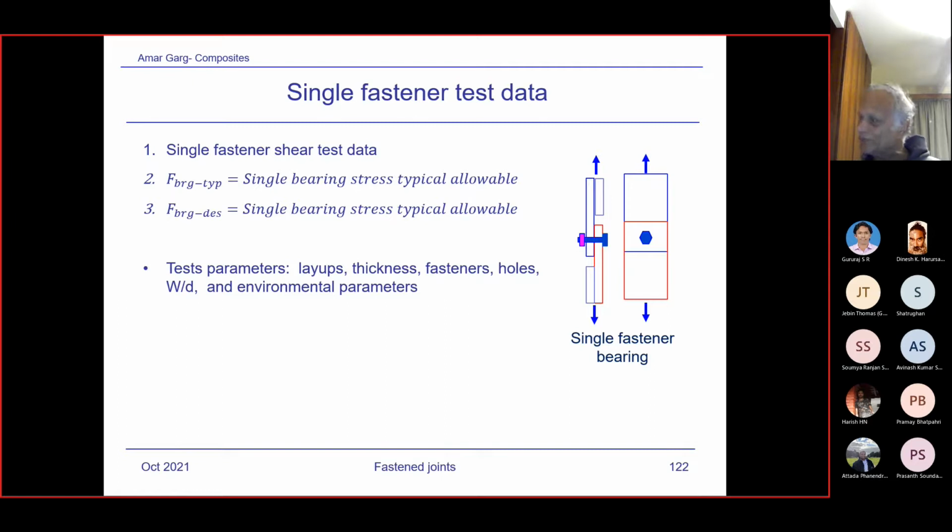Load sorting itself is a big process in the company, because you have to consider every load case, and then decide which part may be critical for which load case. Some may be torsional critical, some may be bending critical, so you have to assess everything together. It's a big process to pinpoint which load cases are critical. After you have sorted out, maybe a dozen, or 10, or 5 cases are critical, then you will analyze the margins for all those load cases.